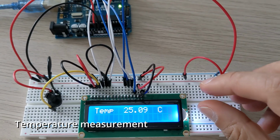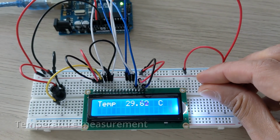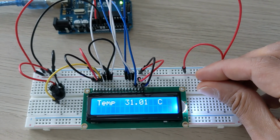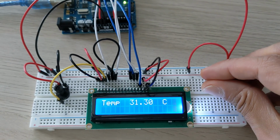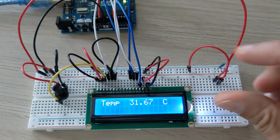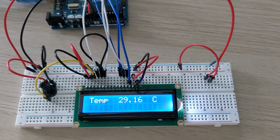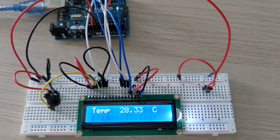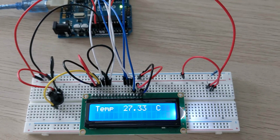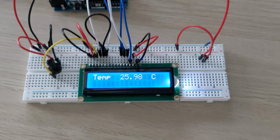With the exact same setup as the last video, save for the slight tweak on the script, by literally replacing the photoresistor with the thermistor, which is yet another variable resistor but sensitive to temperature rather than light, we are able to measure ambient temperature, which here I'm manipulating using my hand's warmth. So now the sensor is cooling off progressively after I stopped pressing it with my fingers. And I'm now attempting to cool it off further by blowing air onto the thermistor until it reaches an equilibrium.